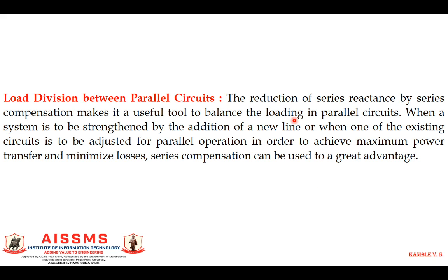So when we have two parallel lines and we have to do a load balance between the two parallel circuits, at that time series compensation is a very useful tool to balance these parallel lines.